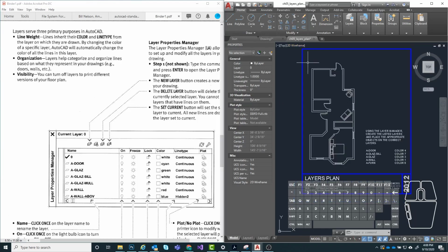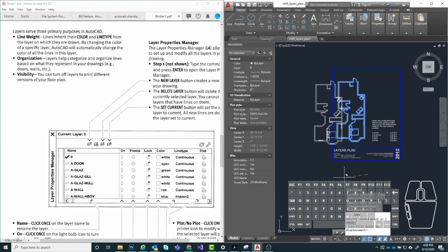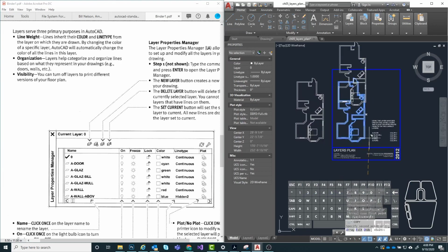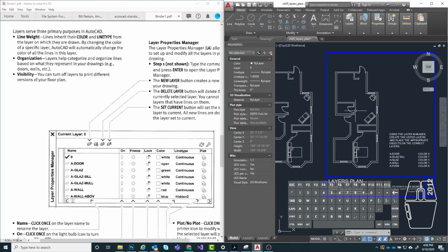So for example, if I were to look at this floor plan here, they would think that I would go here and I would copy. Okay, so make a duplicate of that. And let's say this plan I want to be my furniture plan, so I want to leave the furniture on it as it's shown. But then this plan I want to be my construction plan, and on construction plans we don't show furniture, okay?